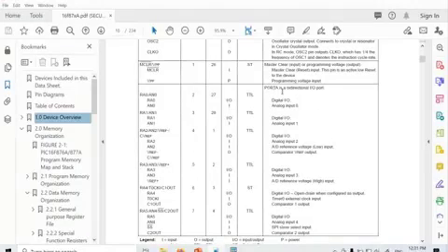The first one is a bidirectional I/O port. This means that RA0 can behave as digital I/O or analog input, so it has two functions for bit A0. For bit A1, it is similar to A0.